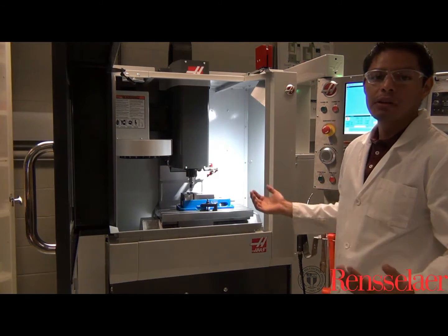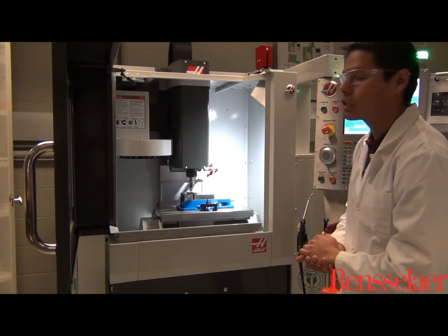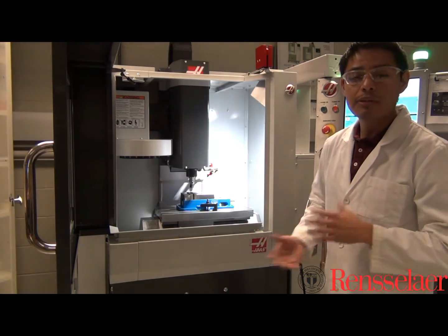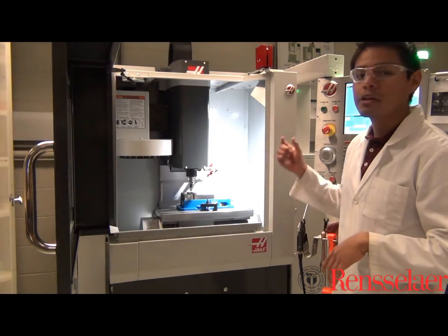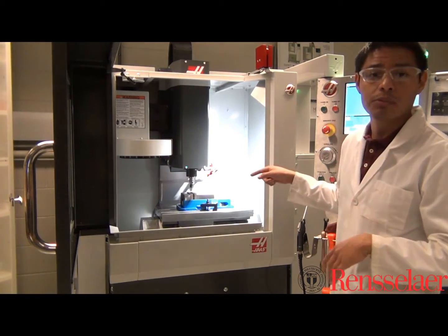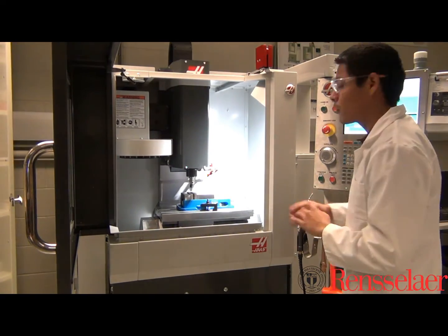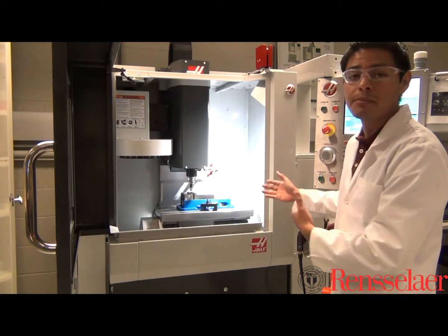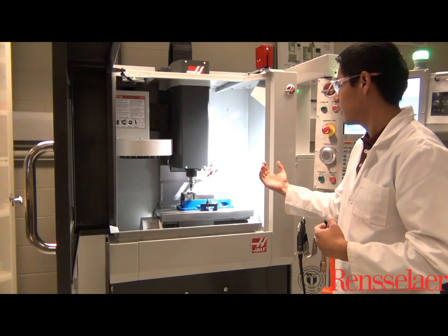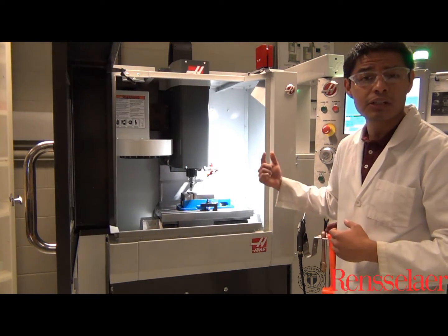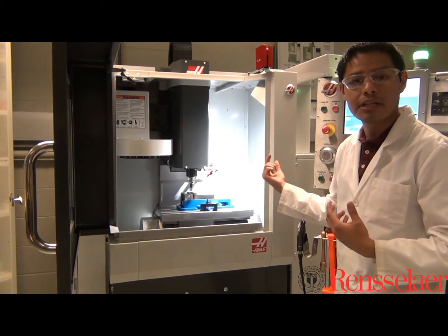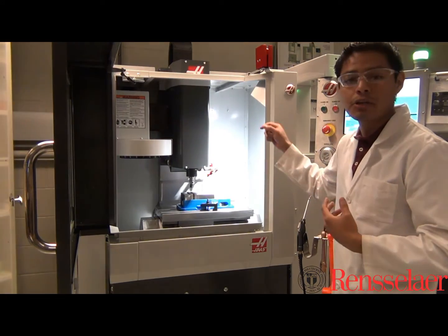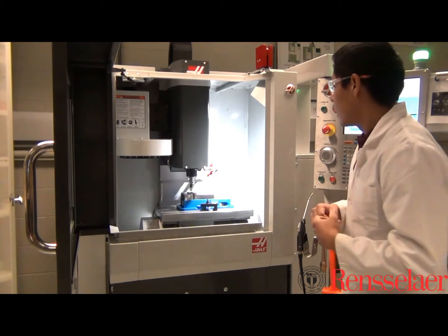So continuing with the process, we're now going to determine the tool length offset. The reason we want to do that is because we want to make sure that the machine knows where the tool tip is relative to the workpiece. Okay, so for the purposes of this demonstration, I changed the first tool to the second tool because it's easier to see the chips that you need to form when you touch off the tool.